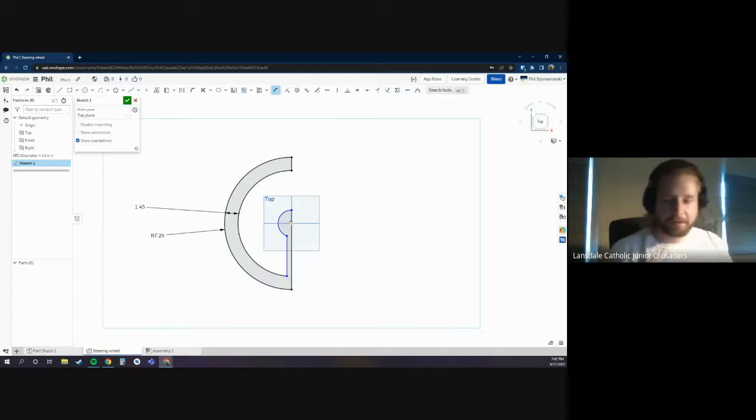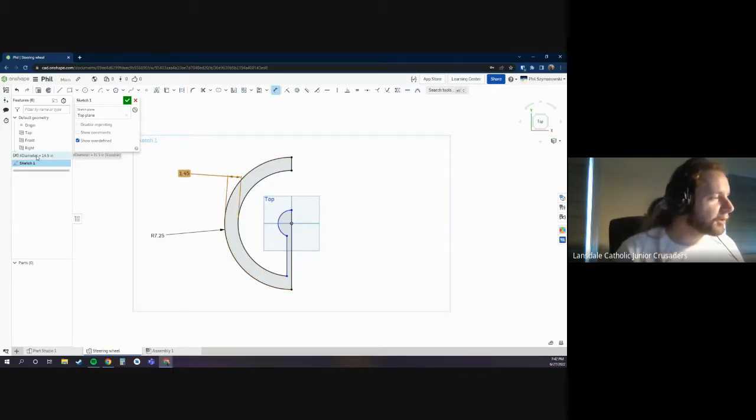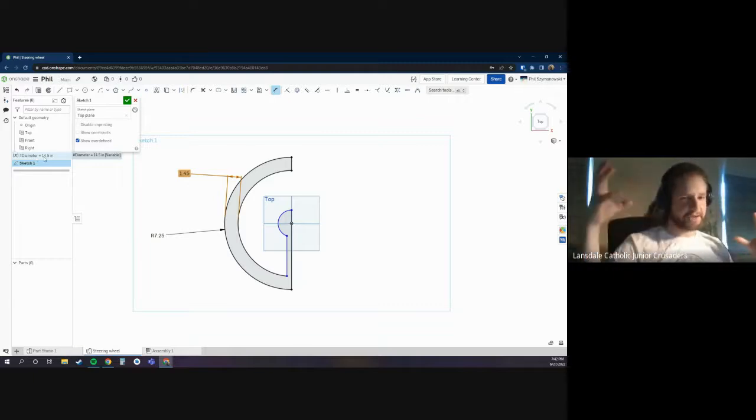If you want your wheel to be able to proportionally scale, or anything to proportionally scale, you'll have to do multipliers or dividers by whatever variable you use. So I made a variable called diameter, and I would like my wheel to stay proportional as it gets larger and smaller, so that the dimensions automatically change.